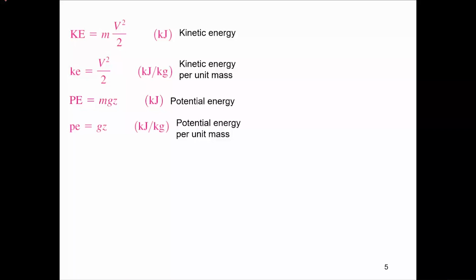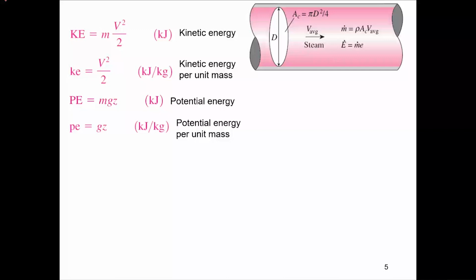Clear enough? Yes. Moving on, you have to be considerate of the fluid flowing through the system. And normally when you are dealing with an open system, you express the fluid flowing through the system in terms of mass flow rate. When you have a dot on top of a dimension, that in thermodynamics would mean that you are referring to that dimension with respect to time. That means m with a dot on top of it means mass flow rate, which is nothing but kg per second.